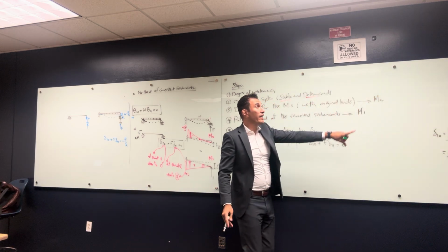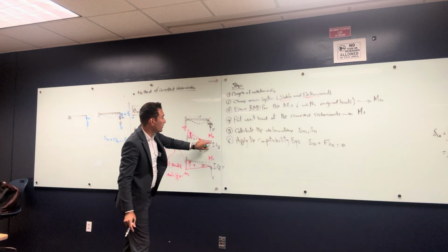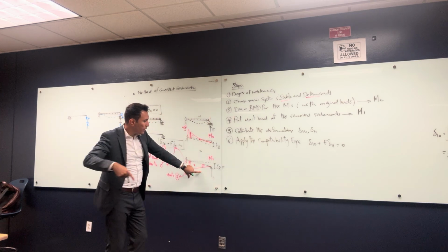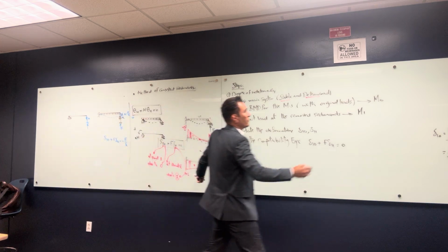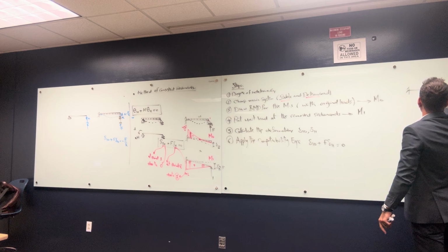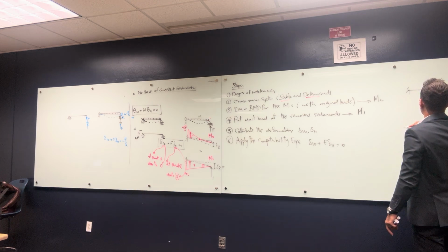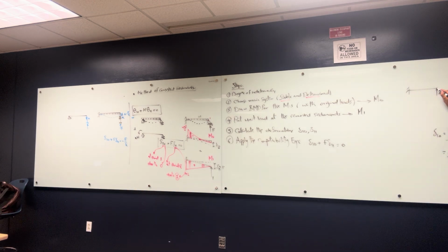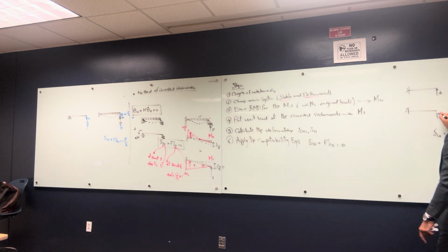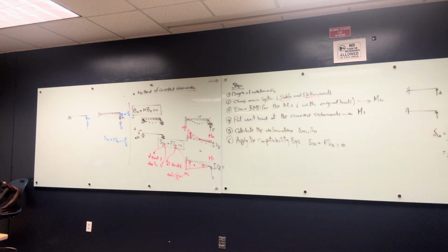So this is how I can get the deformation delta 1O from this load, right? I do the same thing to get delta 11. Delta 11 is a system like this that has a unit load, right? If I want to find the deformation here, I remove this one load and then put another unit load again, right?